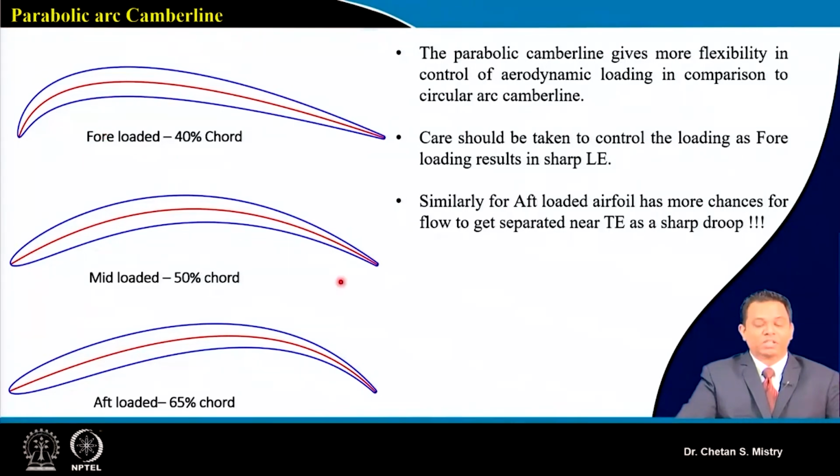Here, if you look, this is what represents my mid loaded configuration. It says 50% chord, that's where we have this camber line. Now, I can change the shape of my aerofoil by using this kind of configuration. It says aft loaded. So, at 65% of my chord, I am having the turning here.